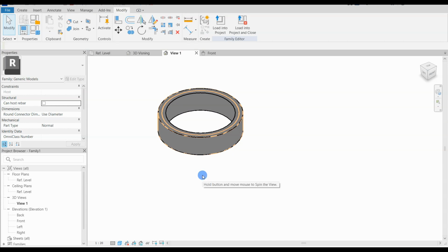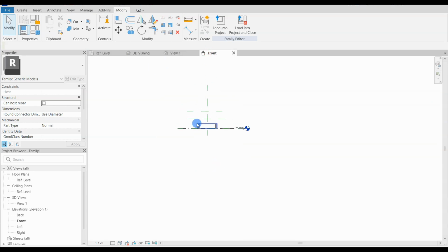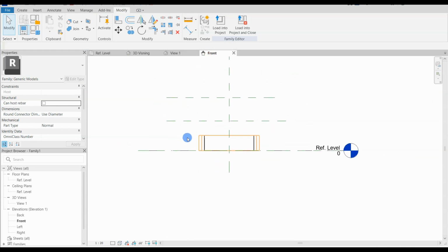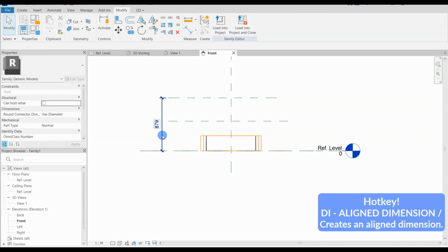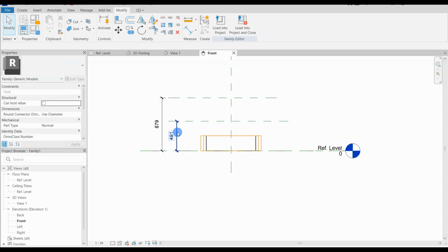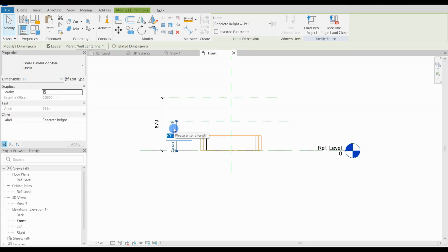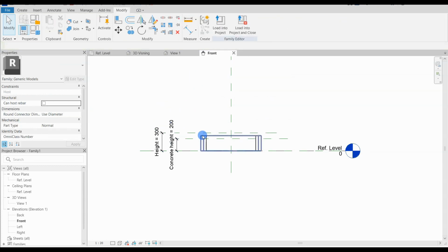It looks correct so far. I do need to constrain the void at the top. In fact, I need to constrain the concrete basin height as well. We go to an elevation view. We add dimension lines to the reference planes that I already placed out and connect them to a parameter. Change the numerical value to adjust the reference plane a little. Connect the other dimension line to a parameter.